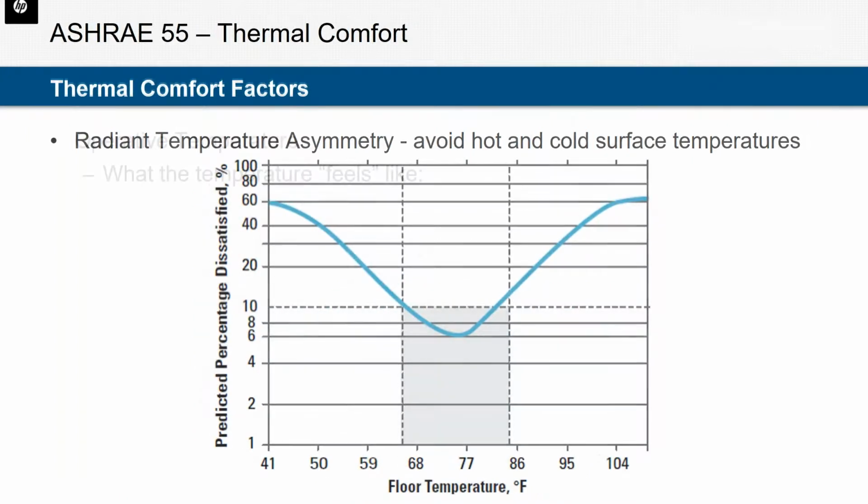The same goes for a floor. If you have a floor temperature that is significantly warmer or significantly colder, that will also trigger a discomfort response. For design purposes, that might affect if you're doing, say, a thermally radiant floor, which can be a very effective design. If you design that floor to be too warm, that will trigger a discomfort response.